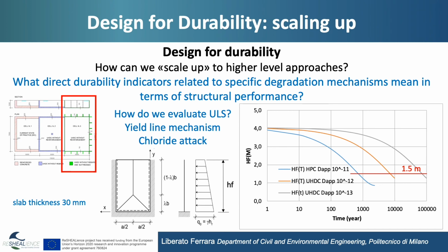So in the graph here, you have the water surcharge over time. You can see that the capacity of this highly structurally redundant structure will guarantee a capacity to resist a wave up to 4 meters, which is inconsistent because the wall is just 1.5 meters.